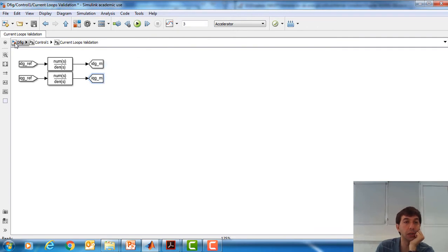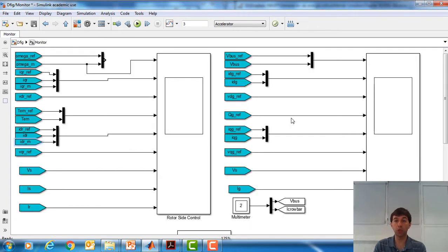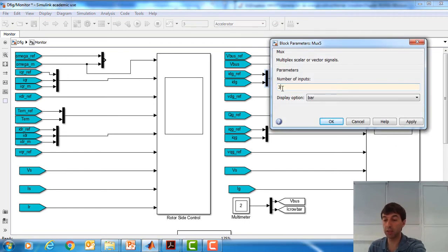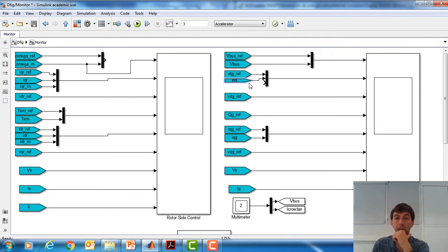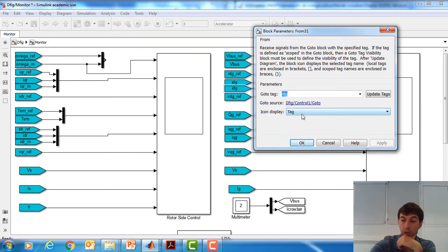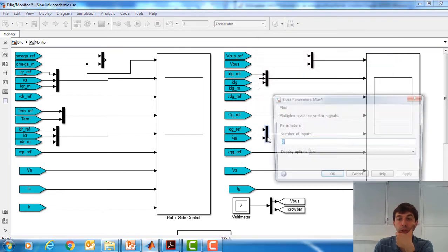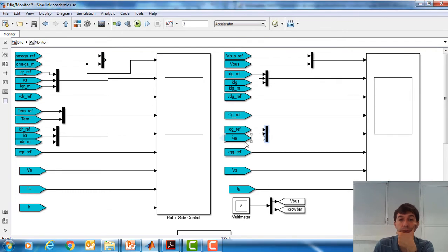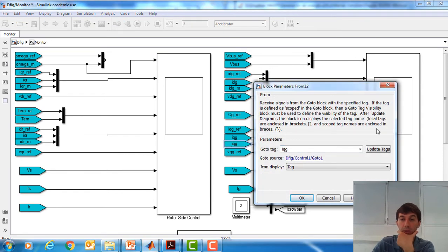Okay, IDG and IQG. And if we go to the monitoring block, again, we go to this grid side converter control, we could do exactly the same and compare the actual or the real values. Let's copy there. That will be model, okay, and here as well we can do the same. Three, sorry, let's do it smaller, and this will be the model approach.